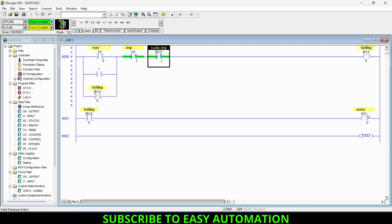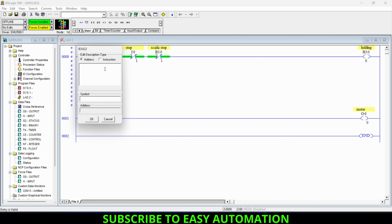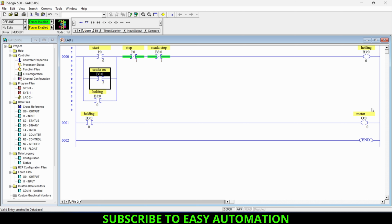So whenever I want to stop this motor from SCADA, I will just toggle this bit high, and for turning on the motor I will use another memory bit and I will name it as SCADA on. So whenever I want to turn on this motor from SCADA, I will just toggle this bit high and our motor will start here. So let's check this program.